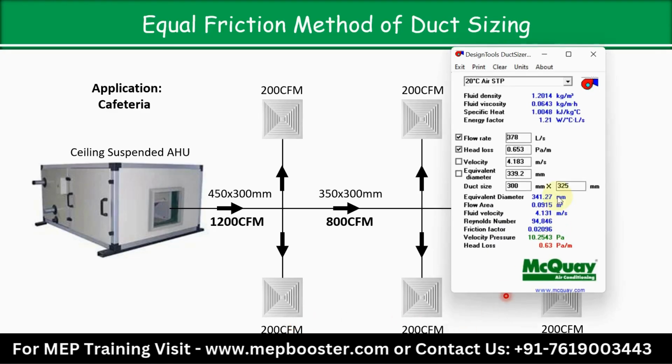Again, here I have opened the McQuay. First we'll change the unit to IPS, write down 400, and now change the unit to metric and see. Right now, when you see the duct size, I have taken the height 300 and the width we are getting is 200. When you calculate the aspect ratio, width by height, you will get a value less than 1. So the condition is not satisfied. Aspect ratio should always be greater than or equal to 1 and less than or equal to 4. Here the aspect ratio value is less than 1.